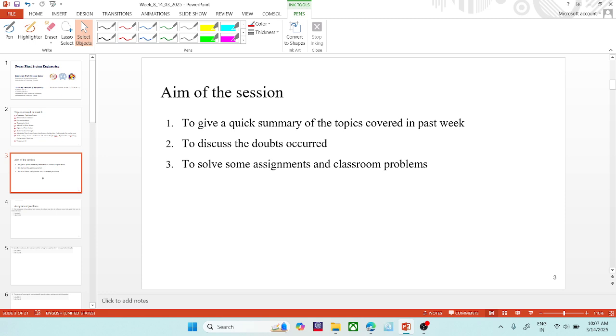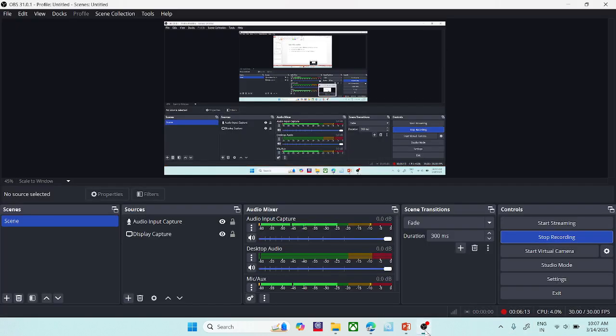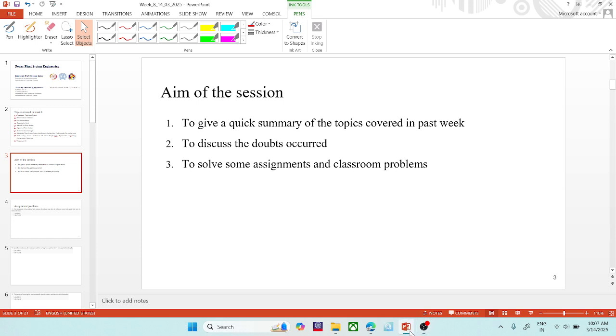In the condenser design, we calculate the length of the tube and number of tubes, and if the length is given, then we have to determine the diameter based on the logarithmic mean temperature difference and the overall heat transfer coefficient U. On the basis of that, we can design a heat exchanger, and here we are talking about the condenser.